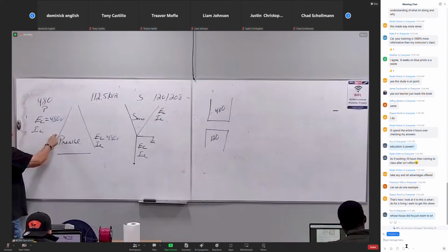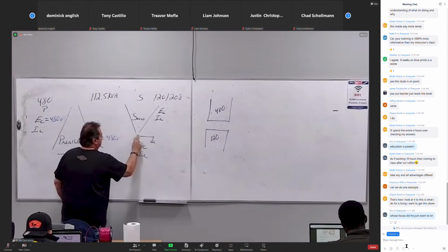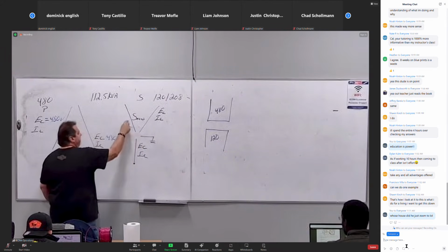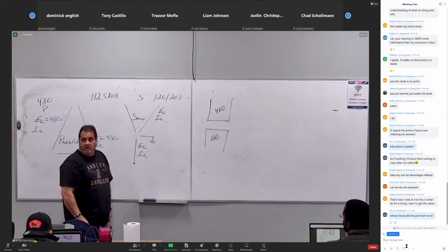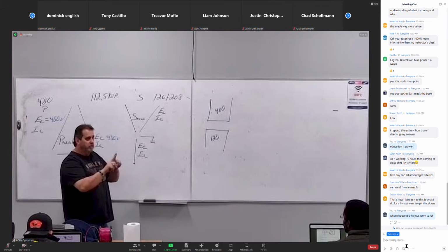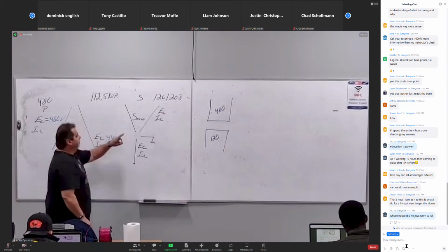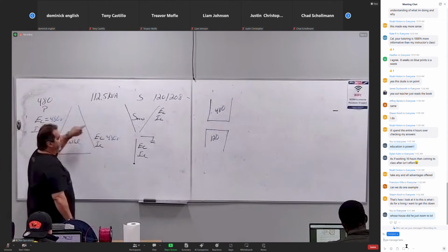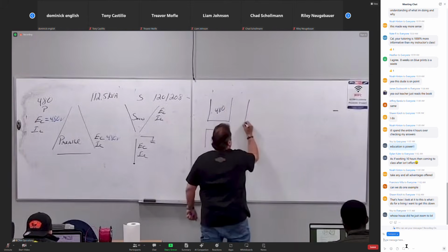This winding is 480 volts connected to or next to that winding, which is 120 volts. The relationship is between the coils. You cannot find turns ratio in a 3-phase transformer from line values. You have to do it from coil values. You know why? Because I have another coil right here.